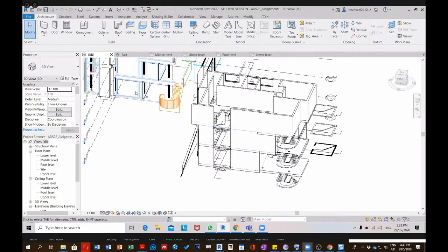Now you need another wall type, generic. It should be 150. Since in the library you don't have this, there is 140 as you can see, but no need for that. So what you can do, you can click again here. Go to edit type. Click on edit type. Now you see the parameters.